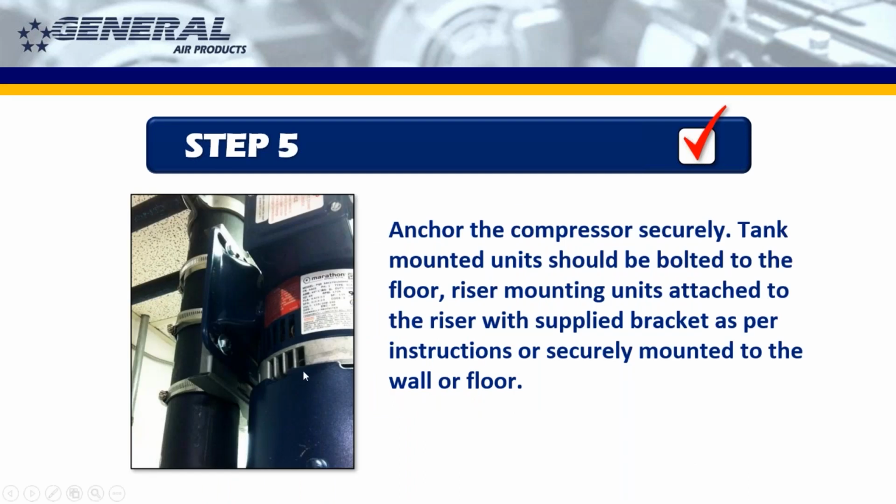Anchor the compressor securely, whether that's to the floor or the wall or the riser in a riser mounting situation. Making sure that that's good and snug. Remember, this is a piece of equipment that vibrates when it runs. If it vibrates and it's loose, that's something for the maintenance end to check. As you check the intake filters, make sure that the thing isn't wobbling while it's running. If there's any room to tighten it down, do so.